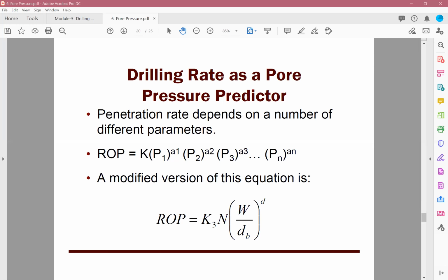The tension, maybe? What's that? The tension on the bit, how much you're going to put? Well, that's not called tension, but it is called weight on bit. Yes, weight on bit is also an important factor. Weight on bit means the weight of all the drill string system applying on your bit. If you have higher weight on bit, you're probably going to drill faster. But there is another factor that combines with weight on bit. What's that?